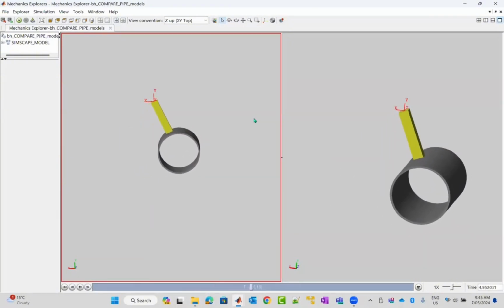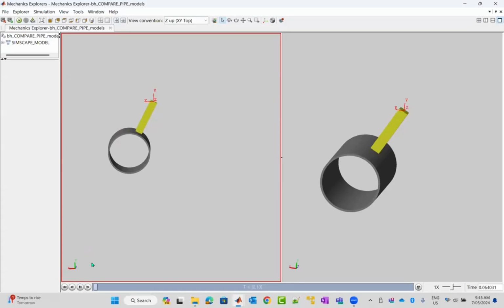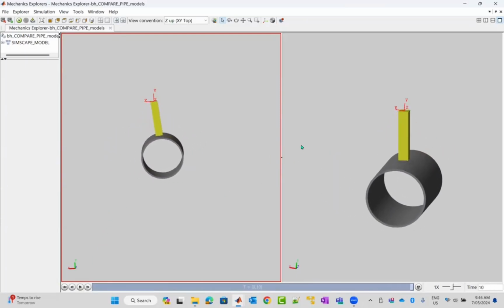And when it does that, hopefully this figure again automatically appears on your screen. So this is something called the Mechanics Explorer. This figure appears when you have Simscape Multibody blocks in a Simulink file, and we do. It's a really nice animation, and it gives you that CAD-like visualization of the motion of the machine. You've got some nice little playback buttons at the bottom of the figure. This is what I would expect to see for this sort of problem.